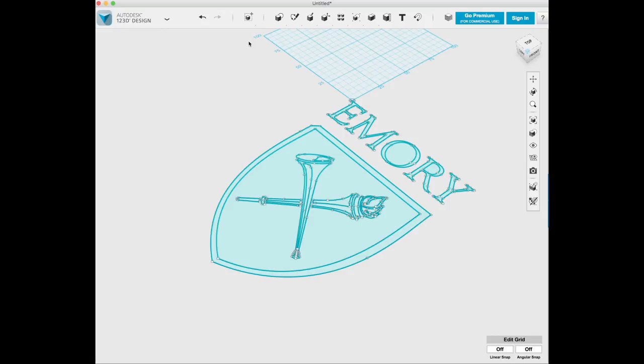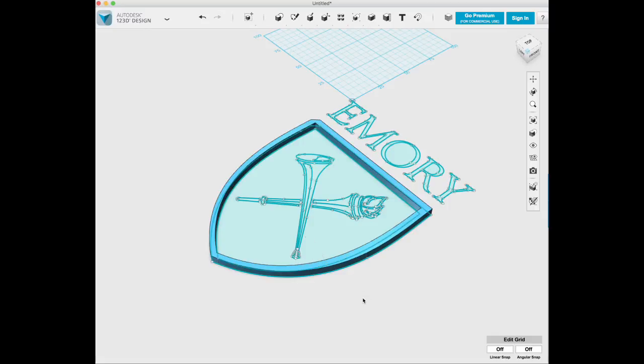So in this particular case, I'm going to be using the extrude tool, which I'll be using with the keyboard shortcut U. So I hit U, it turns into this little box where I choose my face. I then get to choose a distance or a measurement. In this case, I'm going to choose 5 millimeters just to get some space. Pop in my 5, hit enter, and there we go.